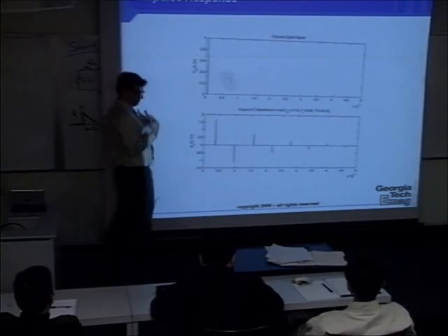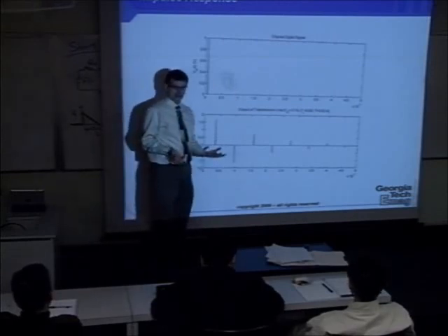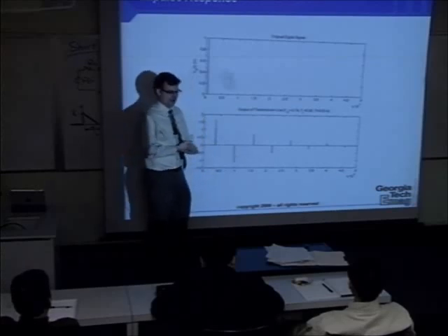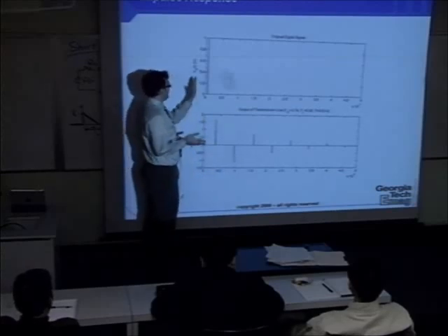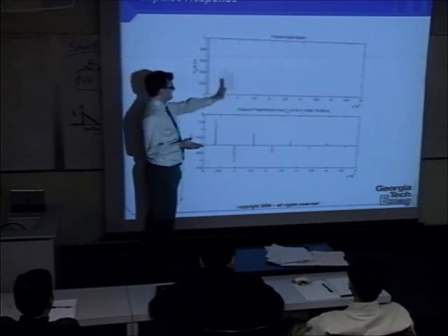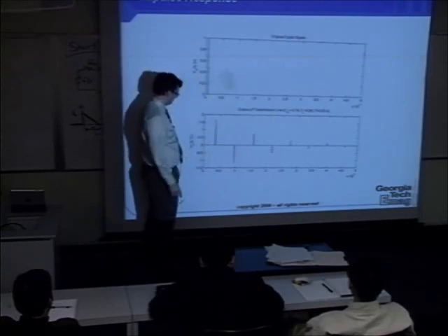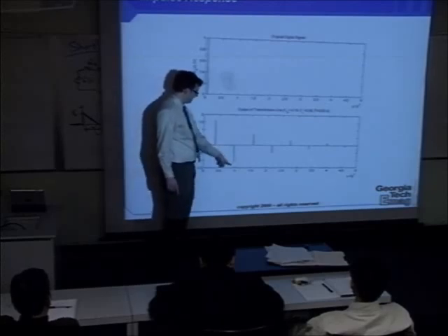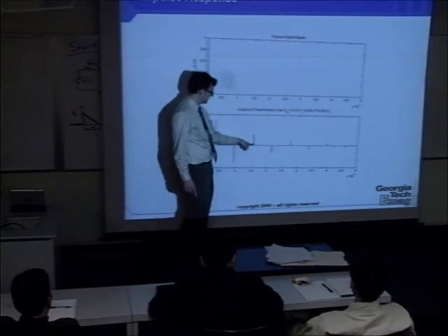So what happens if you put that on a transmission line? I mean, there are some very broadband pulses that you can approximate as a Dirac impulse. And if you send that down on the line, what will happen is that you will trace out the amount of the reflected amplitude. So you see each of these is a Dirac impulse.